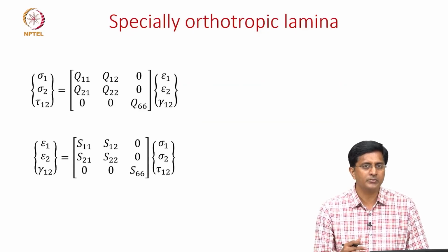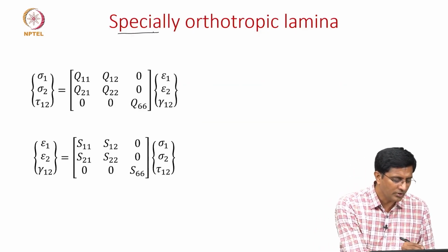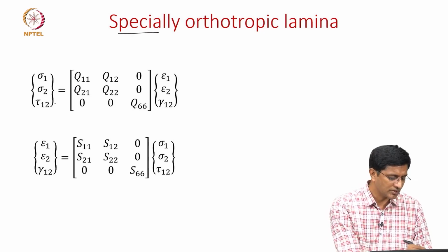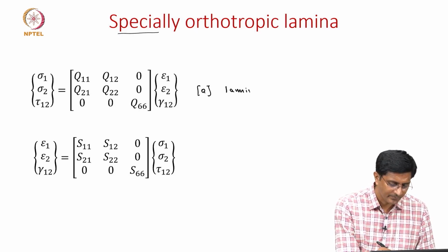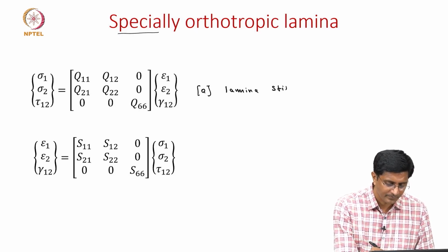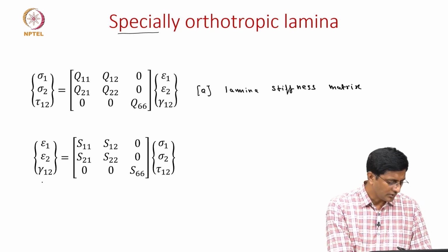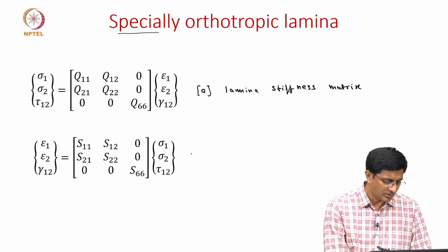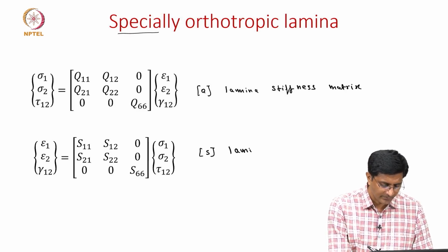We will continue from the previous video, where for a specially orthotropic material we showed the relations between the stress and strain related with this laminar stiffness matrix. And we also showed the relation between the strain and stress using the laminar compliance matrix.